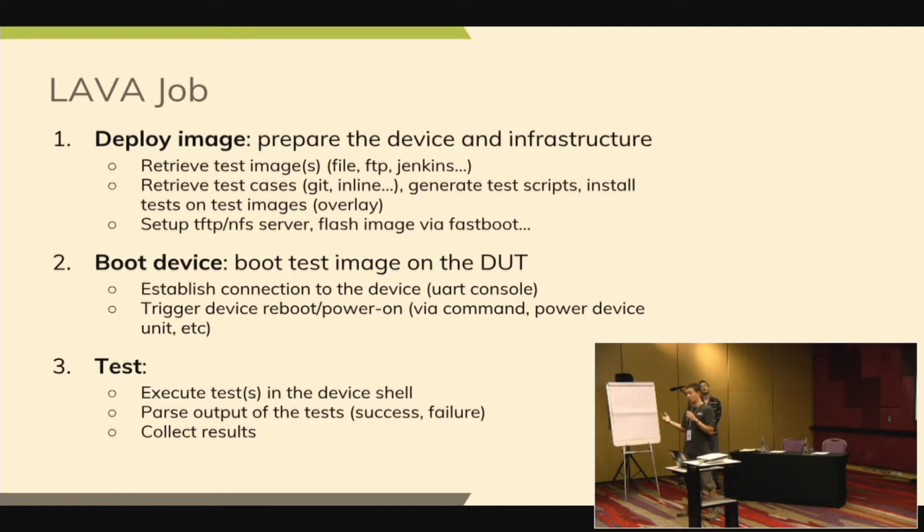Booting means connecting to the serial, powering on the board, using the right tool for sending the binaries, and booting the board, obviously. And testing means running a script on the board itself, collecting the results, and sending them back to the server.